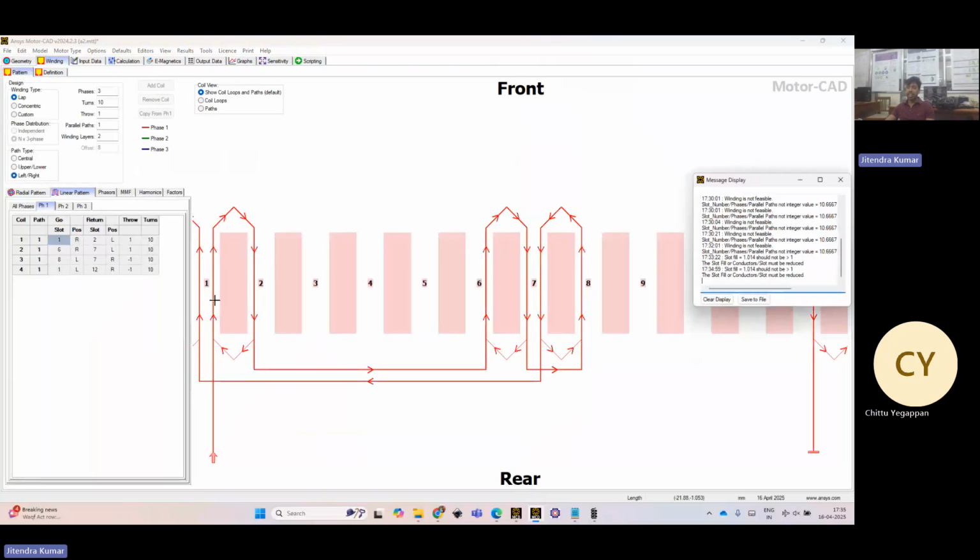So that is like this. And the throw should be slot per pole. So slot per pole is 12 by 10, 1.2. If the slot per pole is a fraction, then you can take 1 or 2, whichever is closer to the integer. Did you get that point, which combinations will not be feasible or possible? Yes, sir. That is how we do that. Any other doubt?